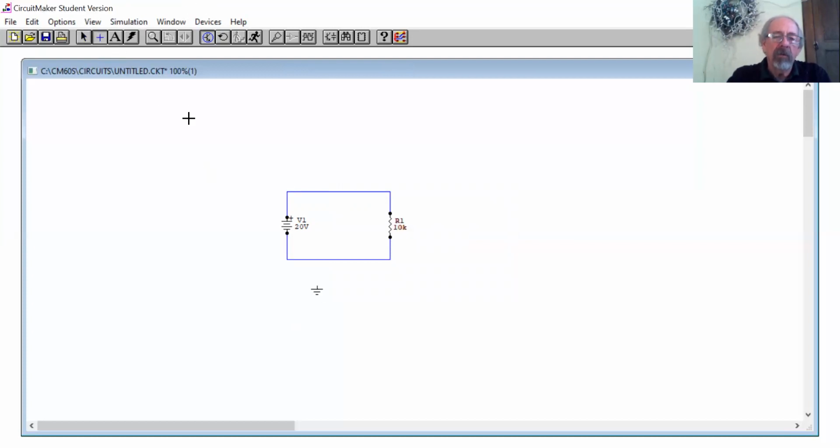I've got to go to the plus for wiring, hover over that, bring it up, and hover on that wire, and I should have a connection. I'll go over and get my arrow cursor back and click anywhere, and it goes to blue. So now I've satisfied it; you always have to have a ground connection. Now I'll go back to the running man, click on it, and didn't see much happen.